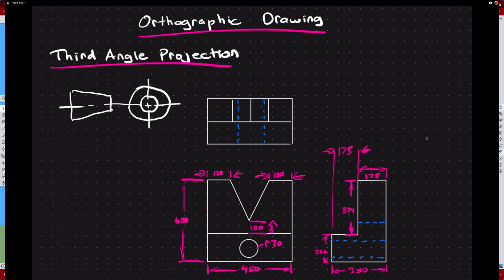Okay, same with at the bottom of this, we can see that that is 350 millimeters. Well, that's going to be the same as this side right here, and this one would be 450, which would be the same as this bottom one down here. So a lot of the dimensions do not need to be put on there. It just clutters it up again, and they become sort of redundant or unnecessary.